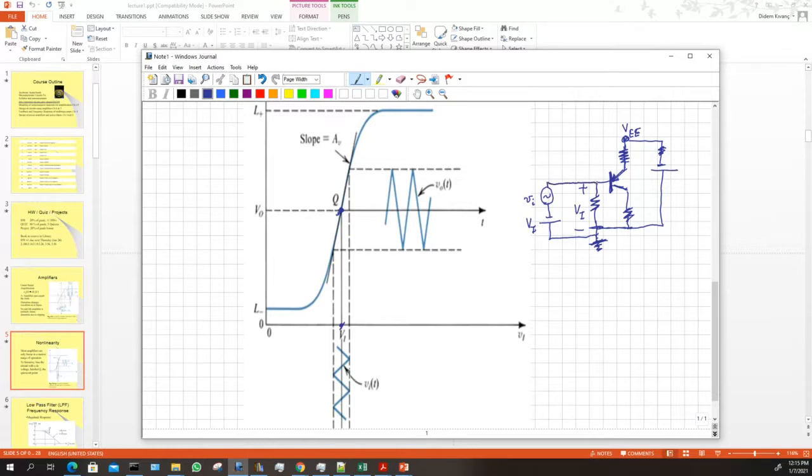But then you don't just apply this voltage, you wiggle it. Okay, so here you're applying this sawtooth wave, and it's adding to the big VI. So your input is going between this level and this level. So now when I map the output, you can see the output's going to be mapped to this voltage. Okay, so it's got amplitude bigger than the input voltage. We can't go too high. We'll go into this area. This is called the saturation region. If you go down here, this is called cutoff region.